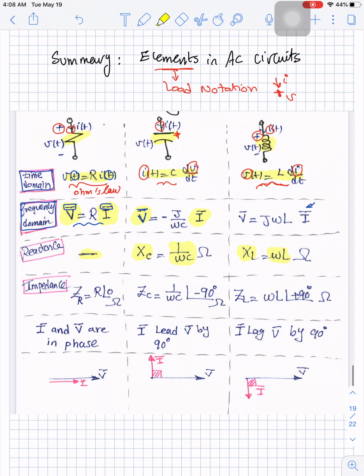So if you have a capacitor C in farad, 1 over omega C is the ohmic resistance of the capacitor. And this is the relation between the voltage magnitude and the current magnitude across the capacitor. For an inductor, the relation between the voltage across it and the current through it as magnitudes, XL, is omega L. So if you have L in henry or C in farad, and you find 1 over omega C or omega L, this is the ohmic resistance in ohm. And now you got rid of farad and henry.